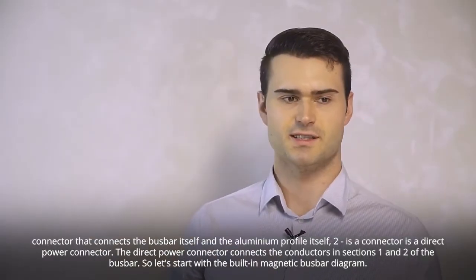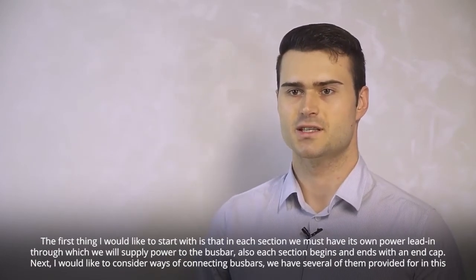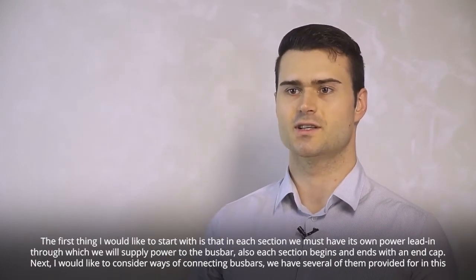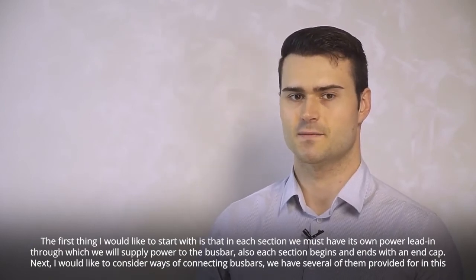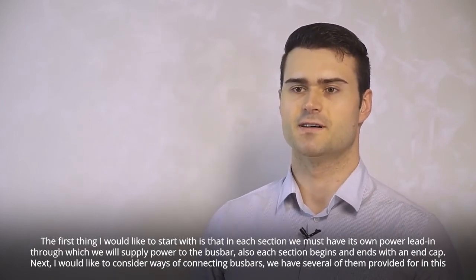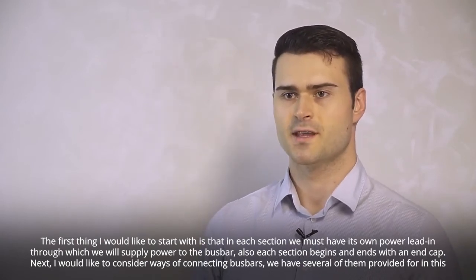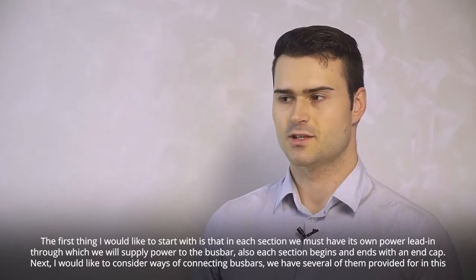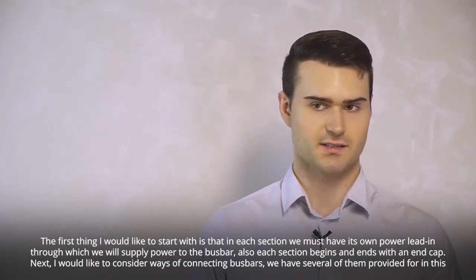So let's start with the built-in magnetic busbar diagram. The first thing I would like to start with is that in each section we must have its own power lead-in through which we will supply power to the busbar. Also, each section begins and ends with an end cap. Next, I would like to consider ways of connecting busbars. We have several of them provided for in this option.